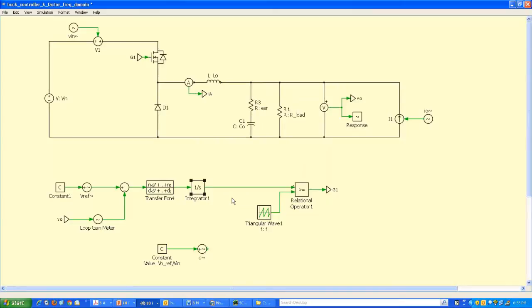Okay, so the next thing that I want to show in Plex is, what we looked at so far is the open loop gain or the loop gain. They are synonymous. I want to next show the closed loop gain. Okay? So you can actually calculate that as GOL over 1 plus GOL for a unity feedback system, but you can actually get that directly from the switch model simulation. So the block that does that: you perturb the V reference itself.